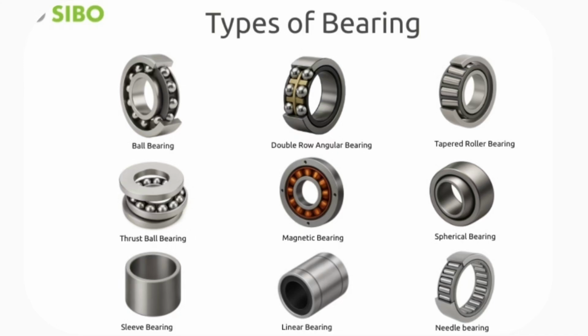Spherical roller bearings: double-row rollers inside a curved outer ring designed for extreme heavy loads and severe shaft misalignment, e.g., wind turbines and heavy machinery. 3. Plain bearings and specialized types. Sleeve, journal and bushing bearings: simple sliding contact bearings with no moving parts inside. Rely on a thin layer of lubrication, oil, grease, or self-lubricating materials like bronze or PTFE, to reduce friction.